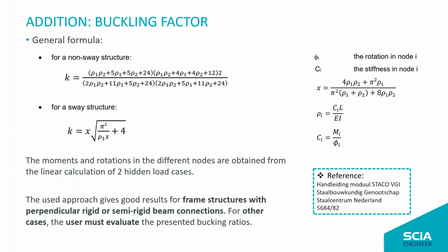and this is how we get to estimate some k-factors. But what I want to stress is that this is an estimation, and especially if your structure does not fit the description here, you should really be careful and check the buckling factors that come out as a result. Now, most often they give us a very big result, so that's rather on the safe side, but still, you should be careful.